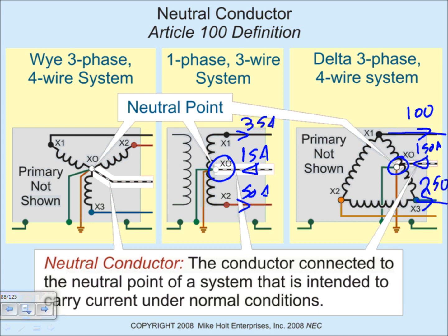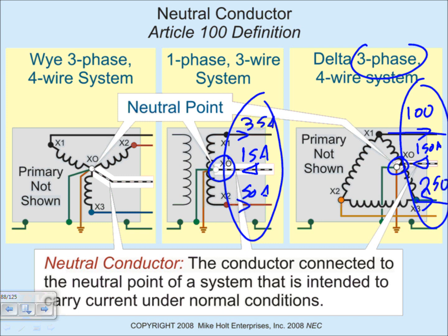These are single phase. Yes, this is a three-phase system, but that part of it acts exactly like this part. Delta center tab, just that part, acts exactly like a single phase. This is what they call the neutral point. You guys are familiar with the neutral point? The conductor connected to the neutral point, which is the point right inside the transformers in the coil, as you can see right in here, is always grounded, going to Mother Earth.